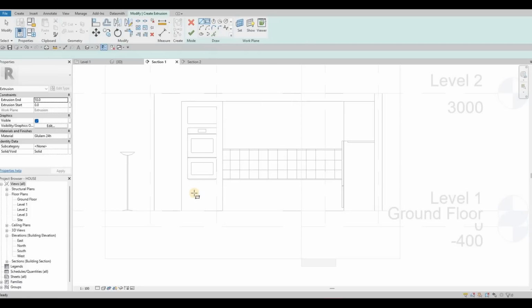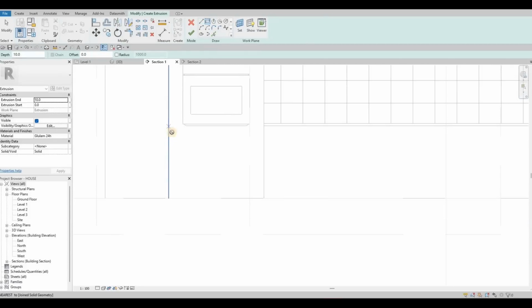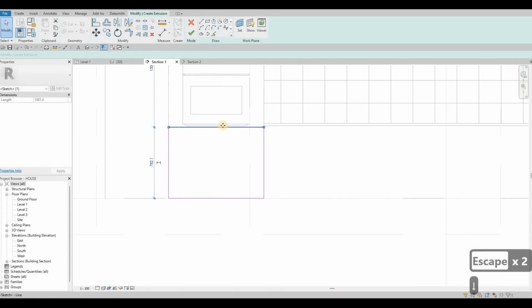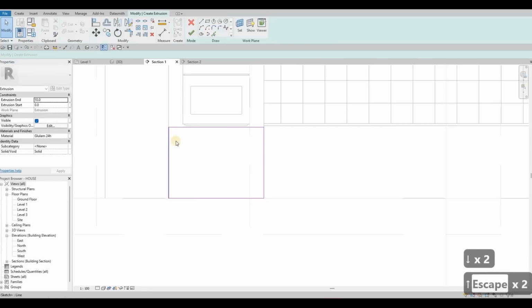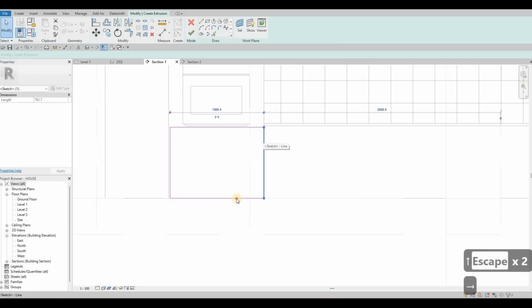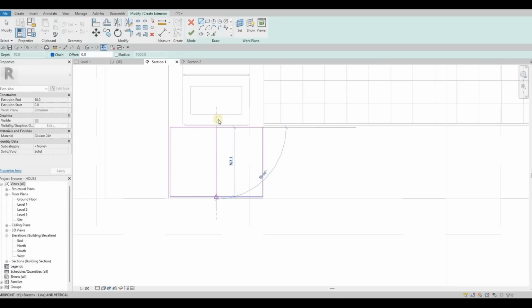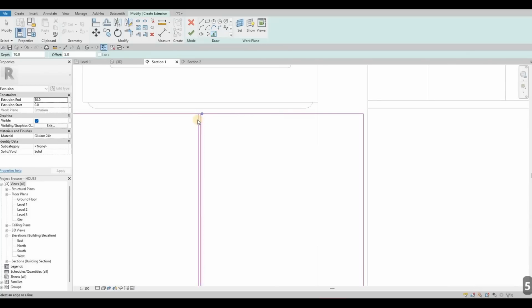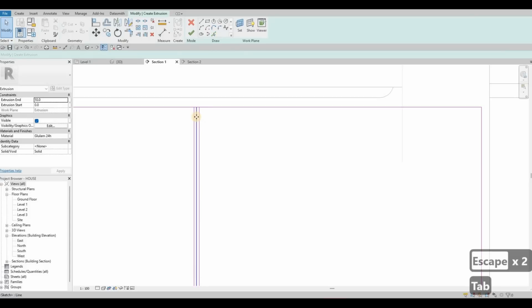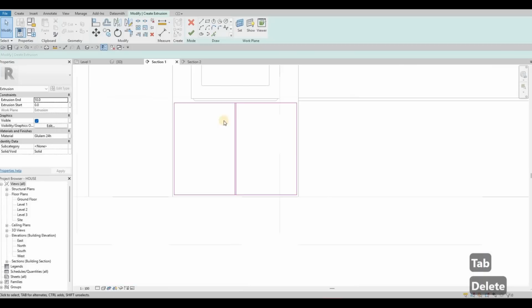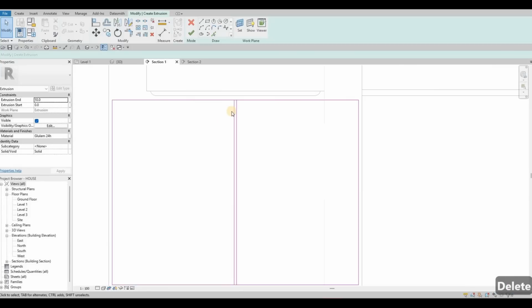And then we're going to put in a rectangle. So now I'm going to add in a rectangle right here. I'm going to lower it a little bit down, and then one notch right here. I'm just using my arrow button so that it's not all the way to the edge. And then I'm going to put in the midpoint right here. And then we could pick in and then put in 5 so that we could see the midpoint of everything. So now we can click on tab, delete this one. So now we have this first half and then this second half, and this is the gap.